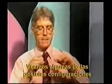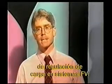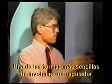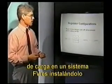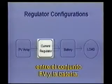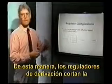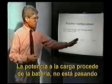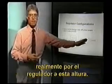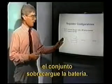Let's take a look at some of the different possible configurations of charge regulation in photovoltaic systems. One of the basic or the simplest ways of involving a charge regulator in a PV system is to install the charge regulator between the photovoltaic array and the battery. This way, the series design of regulators or shunting type of regulators cuts off array power when the battery's full. The power to the load proceeds from the battery. It's not really passing through the regulator at this point. Remember, the regulator is simply preventing the array from overcharging the battery.